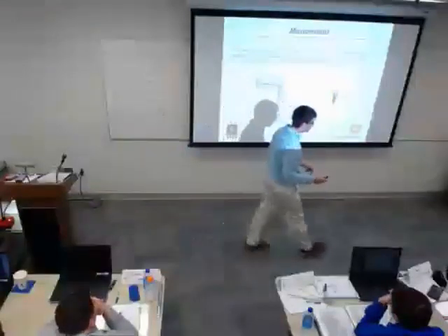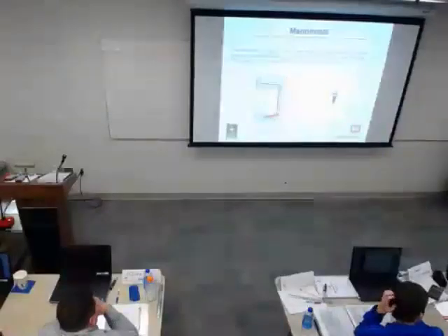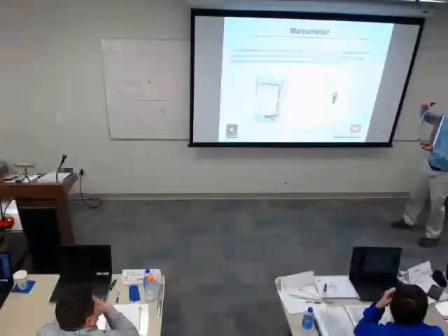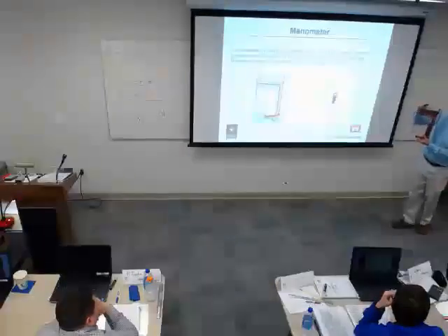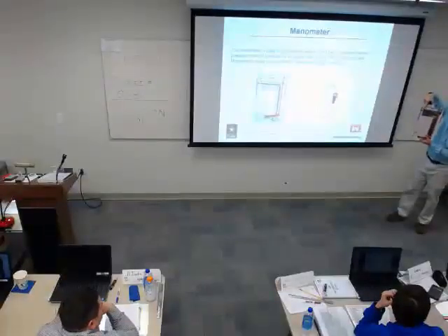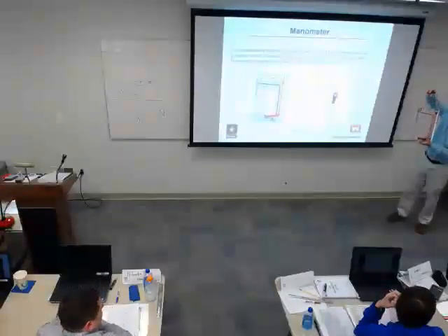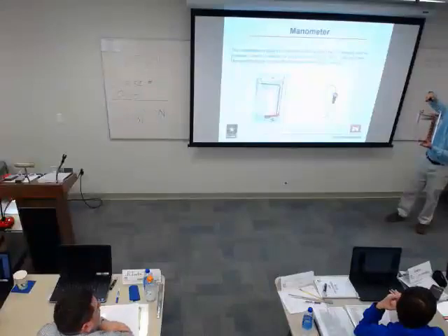Okay, so the pitot tube actually gets hooked up to, you would always see a digital gauge, but for demonstration purposes, I think an old manometer helps visualize it better. So if I hook up a gauge right here, and this thing's too full, it shouldn't have that much fluid in it, but if I hook up something that is generating pressure here, it's going to push this water column down. You can actually see in it. You can kind of visualize that pressure would force that water column down.